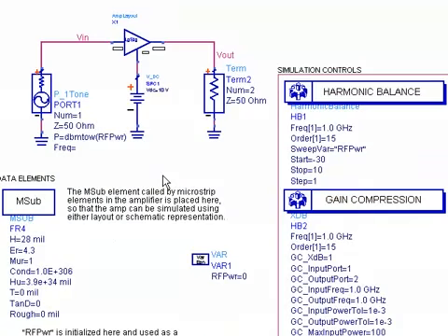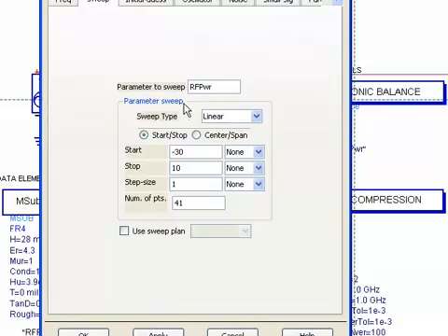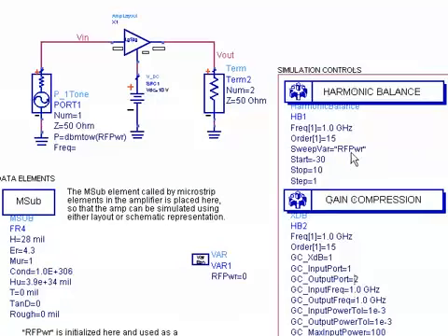It's right there. And looking closely, you can see that the source is set up power equals dBm to watts RF power. This is a variable. So a variable was inserted down here, and it's titled RF power equals 0. It doesn't matter what you set it to because it's going to be swept, and it's swept in the harmonic balance controller. Notice the sweep tab shows RF power minus 30 to 10 in steps of 1 dBm.